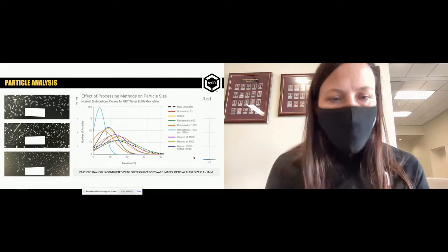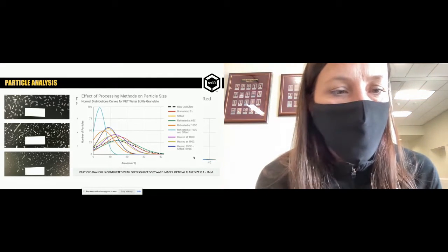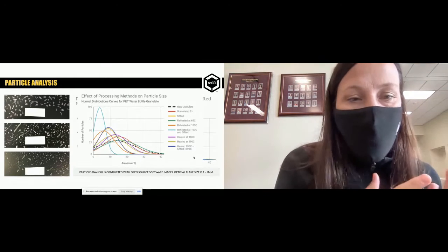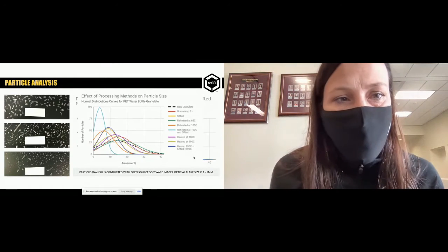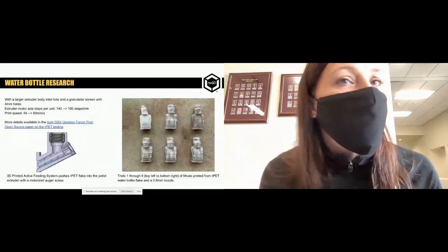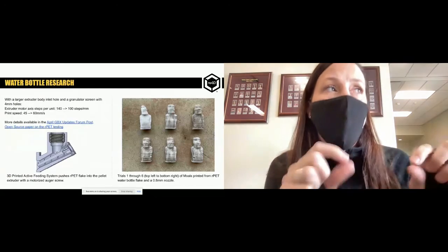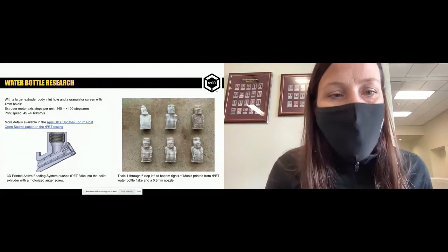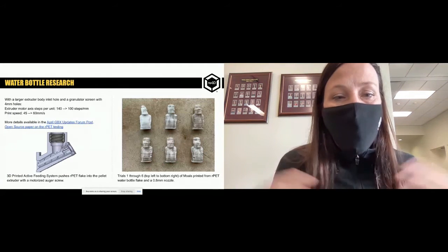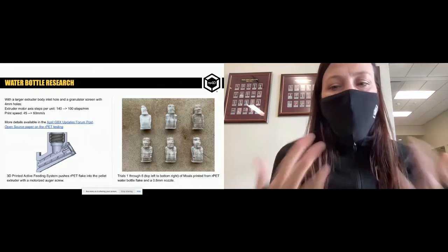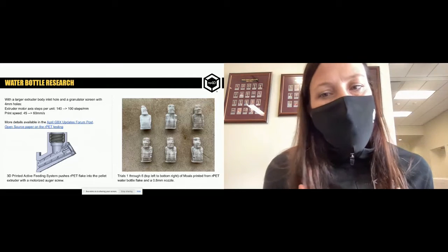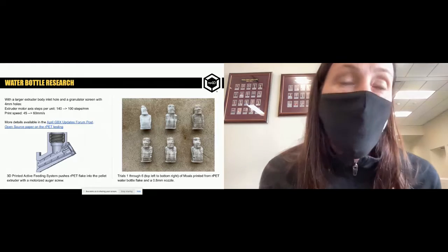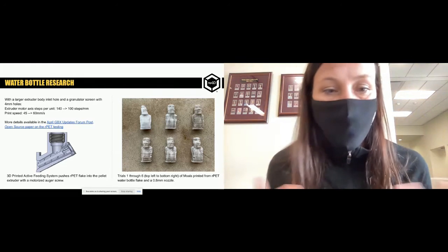As you dig into it, though, there's a lot of science that goes into the regrind, thinking about the size that's feasible versus not, whether you can use dust or you have to focus on larger formats. And we've also learned that not all trash is equal. For example, water bottles have different thicknesses. Some curve, some are more flat. So there's a lot of science even in the granulation and the sifting that may be needed. We've also learned, particularly with water bottles and some of these tougher manufacturing forms of waste, you may have to deal with crystallization, like real chemistry can happen in there, or it may have char from an additive.